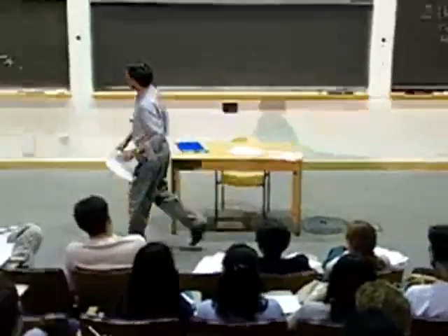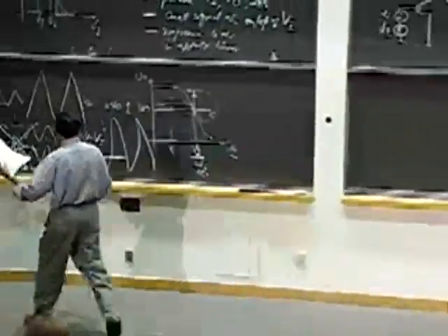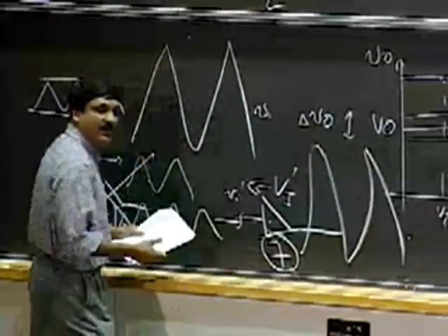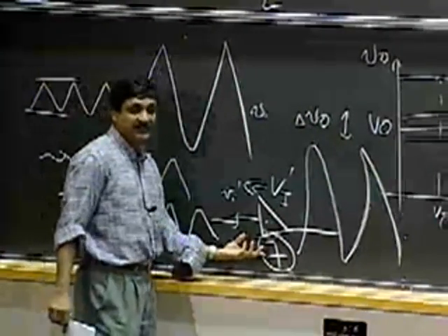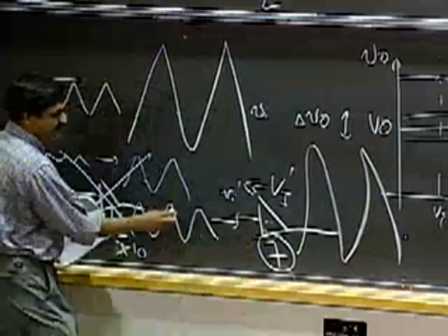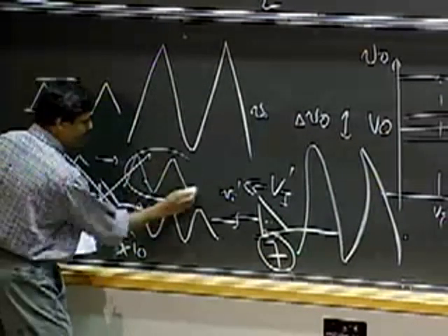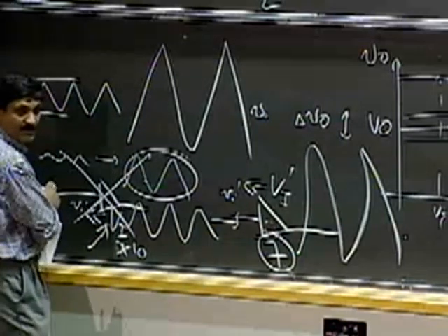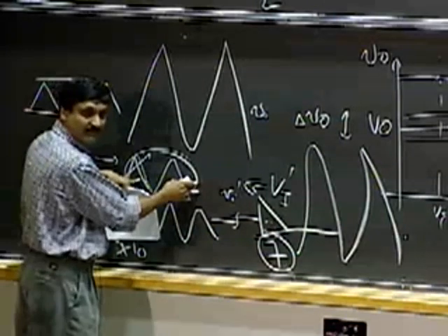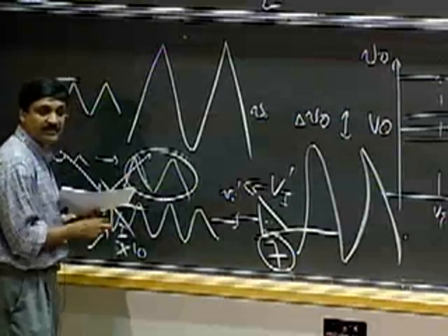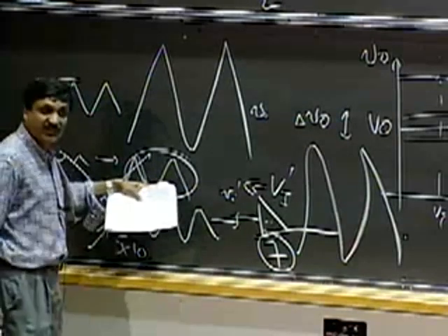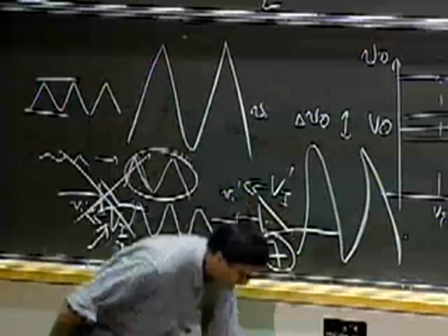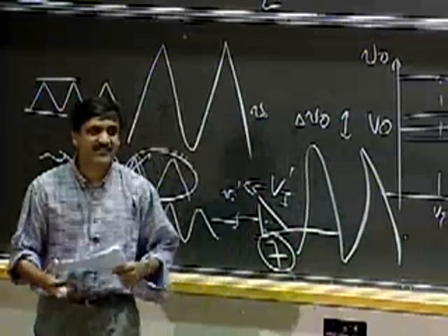I'll just explain. I will not be able to pass this to the big amplifier to begin with because this may give me a gain of just a factor of 7. However, if I have a signal that's this big to begin with, then I may just need this amplifier. I don't need the smaller guy. If I had a strong sensor that produced a strong signal to begin with, I can deal with just a single stage. I don't need 2 stages. It's all a matter of design, and it's actually a fun design exercise.